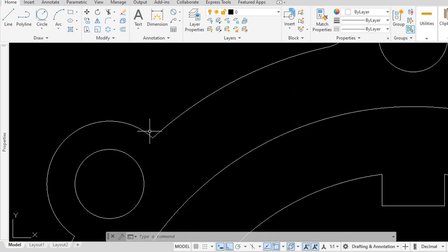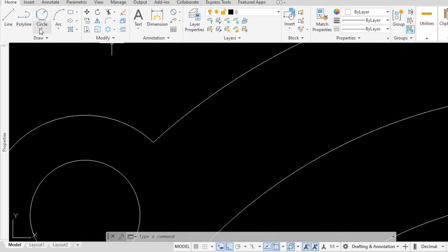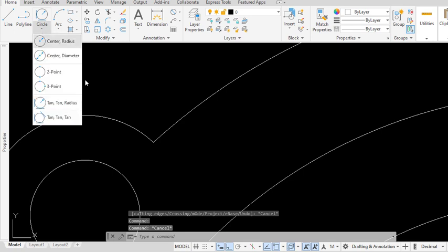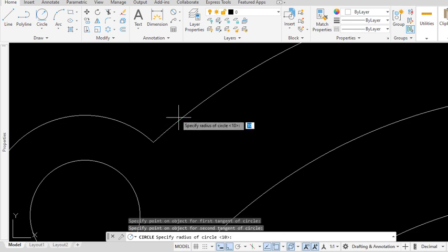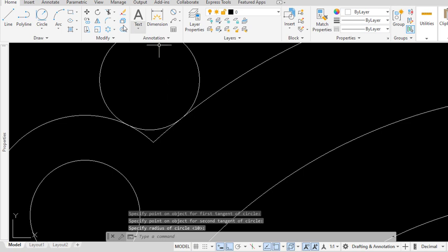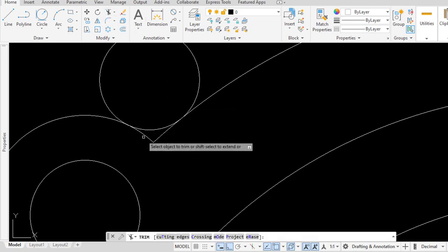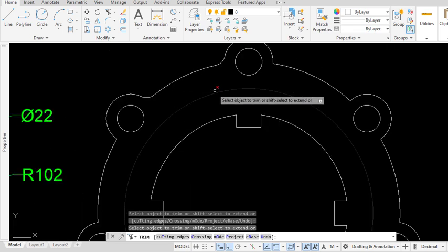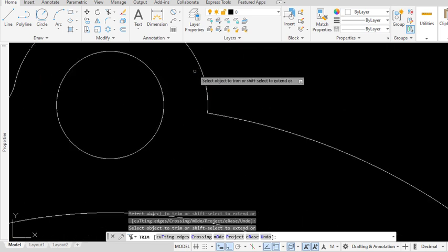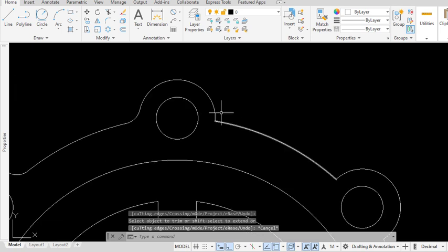So again, I can repeat on this one. So you just select the circle turn. You click one side where it is starting, and then the next, so turn, and then select turn radius. Select, click one side, click the other one, and then put radius to be 10. Enter. So the circle appears, and then you trim this one, and then we trim this. So we have a radius of 10. You can repeat this one for the final time.